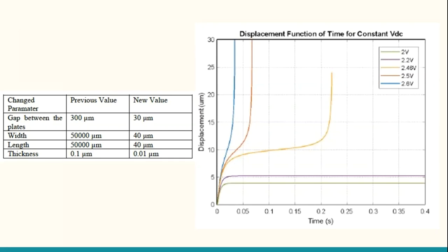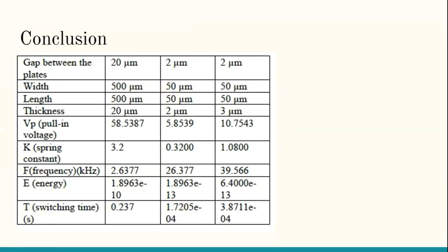While reducing the size of the capacitor, we do not want to lose stiffness, and it can be achieved using appropriate scaling factors. Since we reduce the length of the capacitor, it will increase the stiffness even though width and thickness are reduced, because we use different and appropriate scaling factors for these parameters.